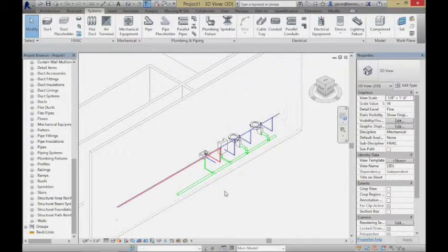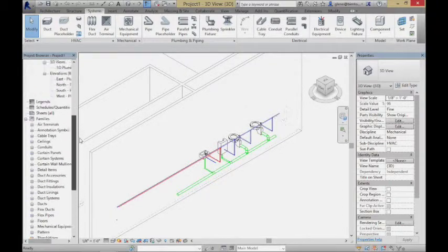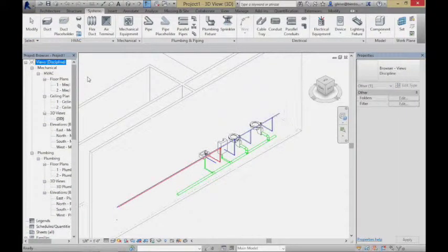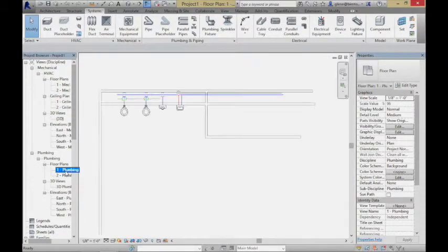Often I'll start with the notion of putting a riser in, some sort of vertical connection between the different floors. It'll typically be one of the first things that I do. The reason I like that is that I'm moving back from the source or the end point to all the different fixtures that are generating the loads, and it's nice to think about doing that in a very systematic way.